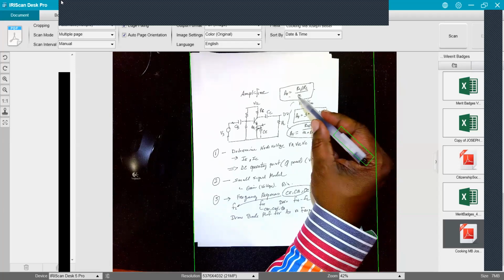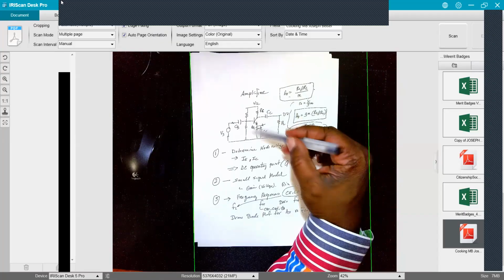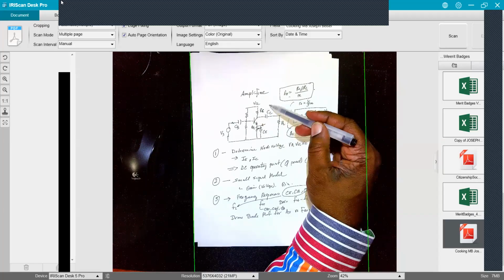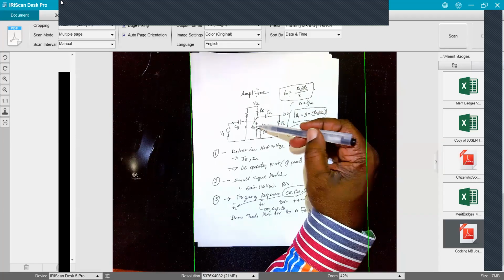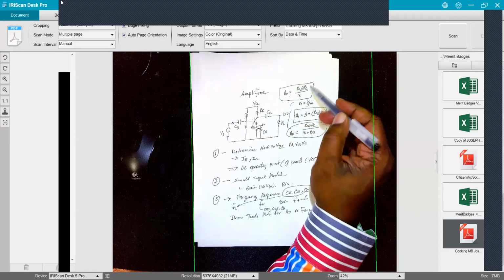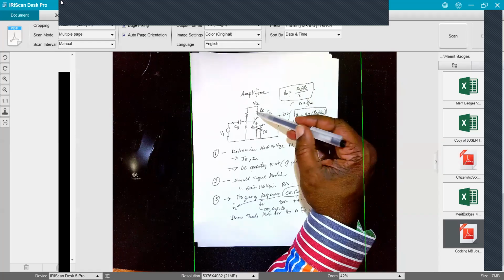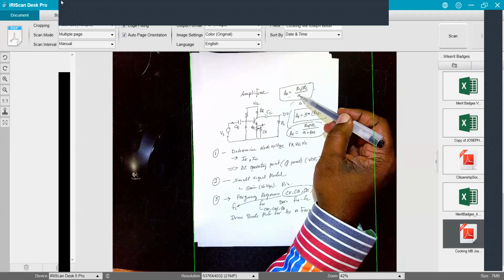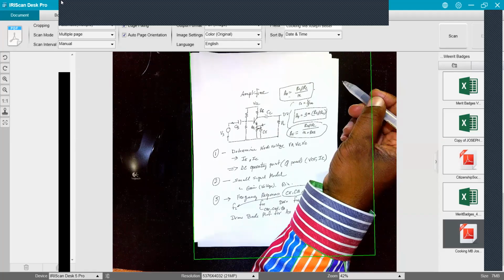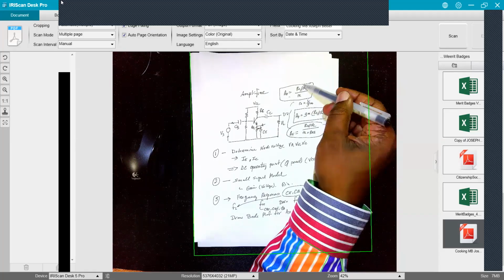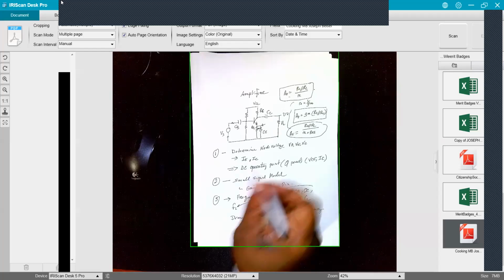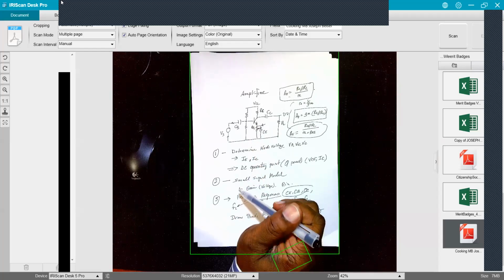So sometimes you might want to write it like this, but in general, the gain in this amplifier is approximately the impedance, the resistance looking out this node divided by the resistance looking into this node, RE. And so these are just values on the schematic. And if you calculate RE, which is 1 over GM, then you can do a quick estimate of what the gain of this circuit is without calculating all these operating points and things, assuming that everything is biased up right.